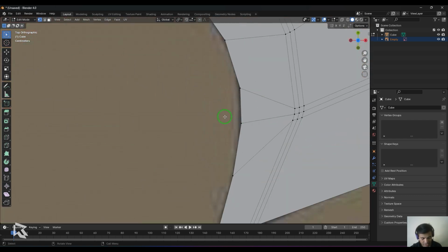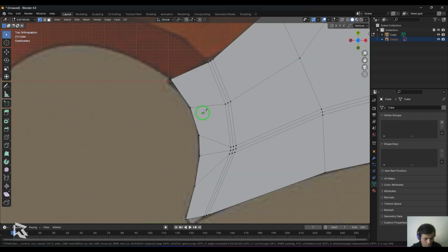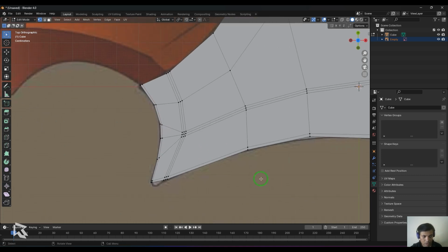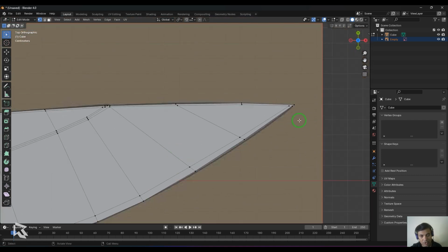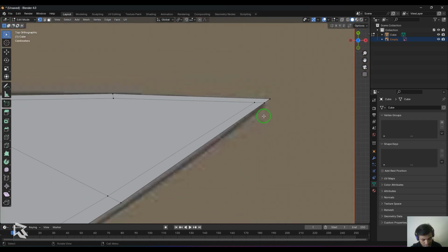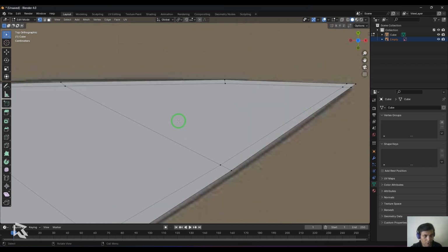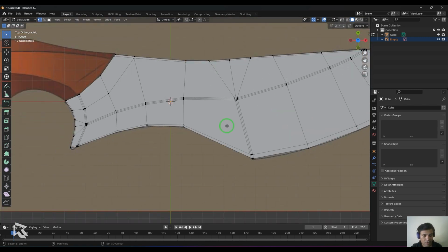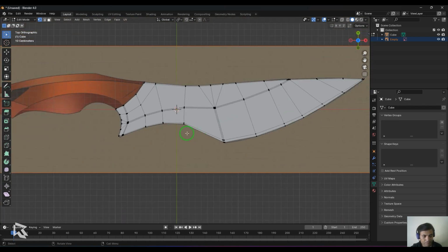So I press K for the knife tool, or you can use this Control R for adding the loop. And then that adds up a line to the border there. Now I need to check how this line is going all the way to that particular corner. I press K and then connect those lines, and then you should be able to see 1, 2, 3, 4. There's no problem in terms of quads and all that are concerned. So let me select all these points here.